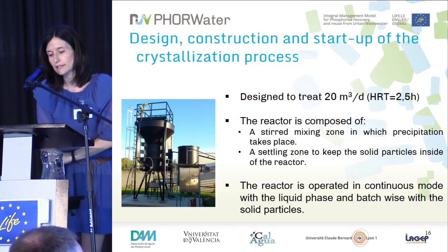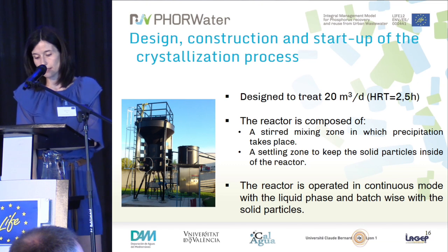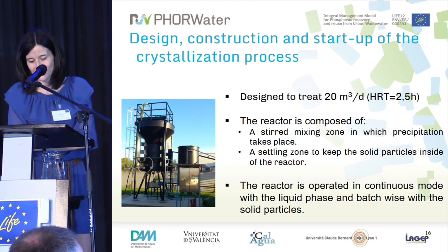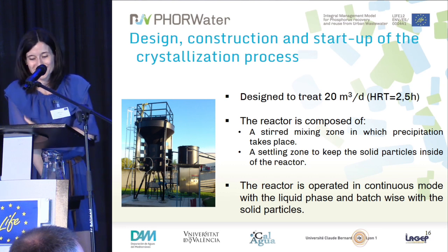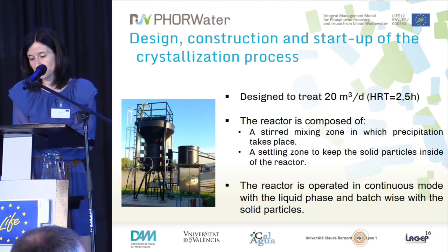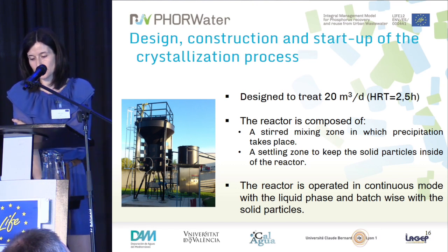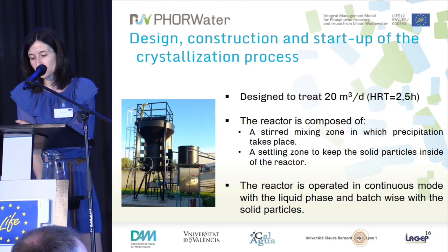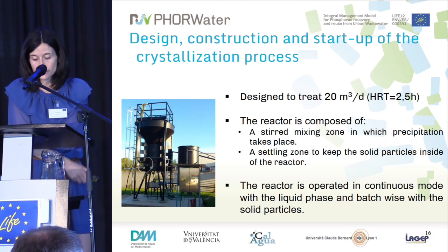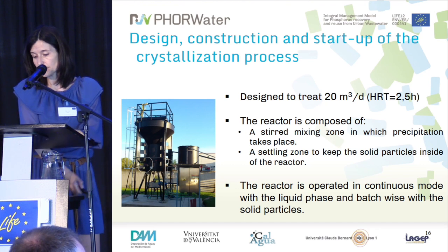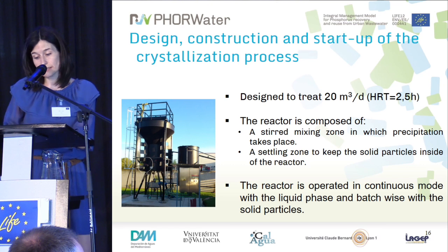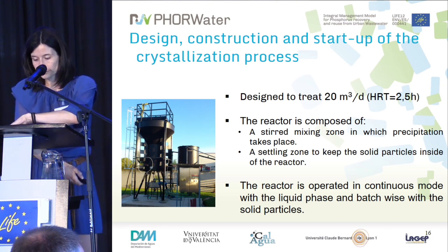So we finally decided to design, well, not a lab scale, but not a full scale, a reactor. It's been designed for 20 cubic meters per day with a hydraulic retention time of 2.5 hours. And this reactor is a complete stirred mixing tank with the settling zone on the top.